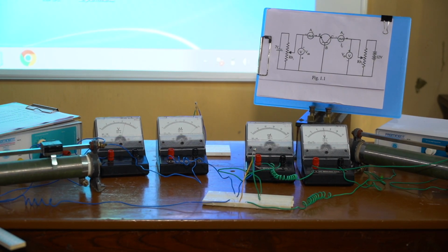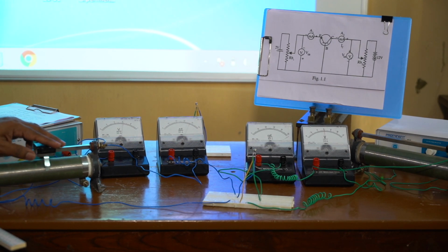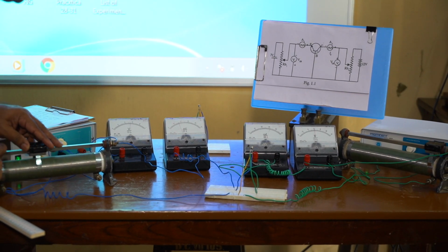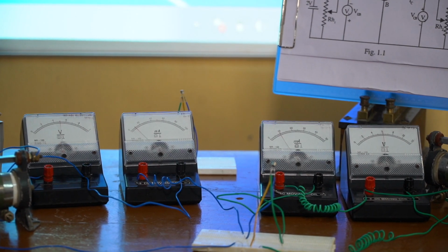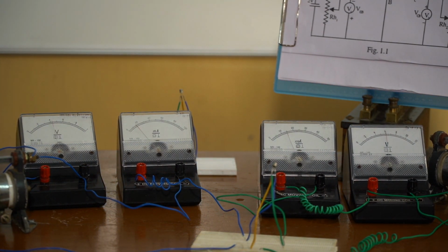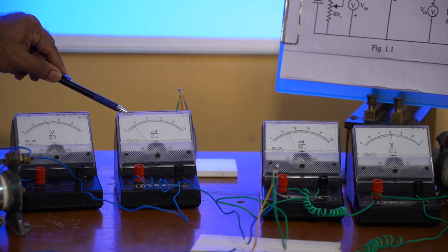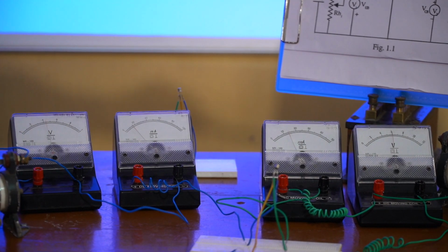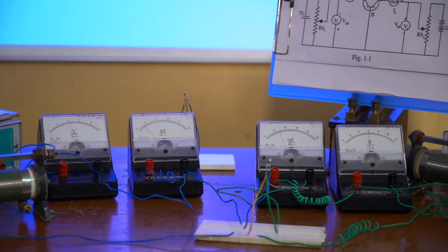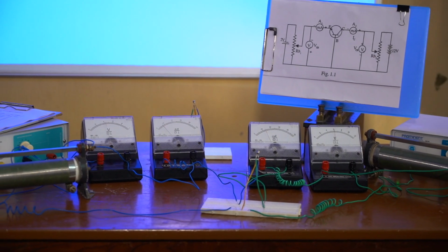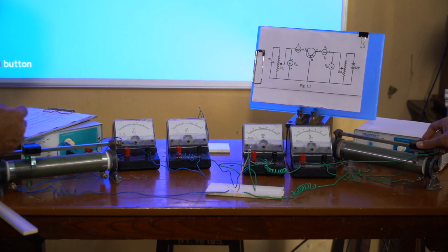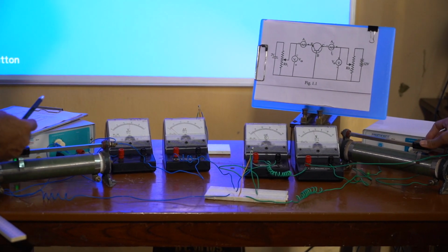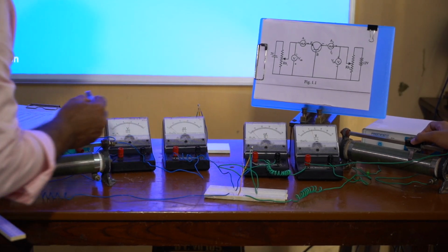Now we want to plot the output characteristics. For that, the input side is maintained constant. That means the input current is maintained at 10 milliampere. Now with the help of the rheostat RH1, the input current IE is maintained at say 10 milliampere. Now with the help of RH2, we are changing and finding the value of the collector current IC. Now we can change the collector base voltage. Initially find what the value is. Now bring it to 0.2 volt.